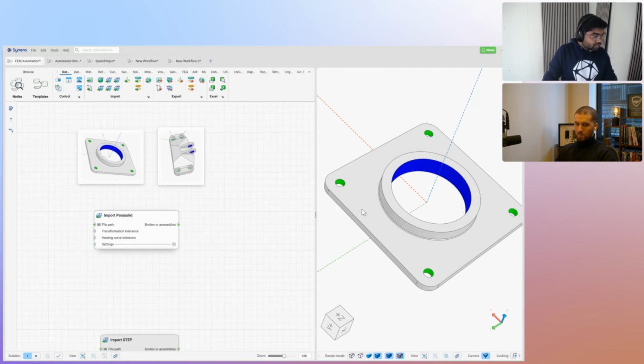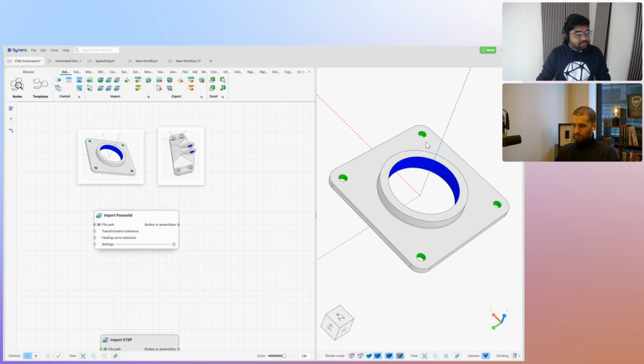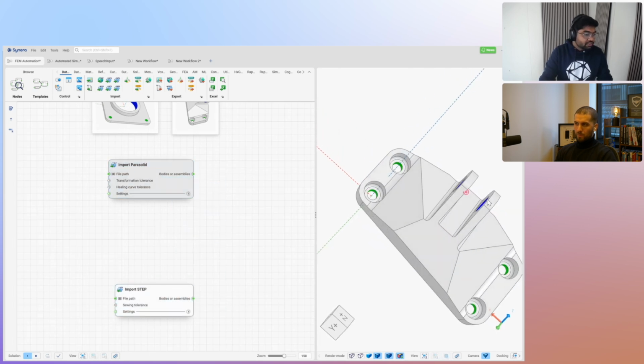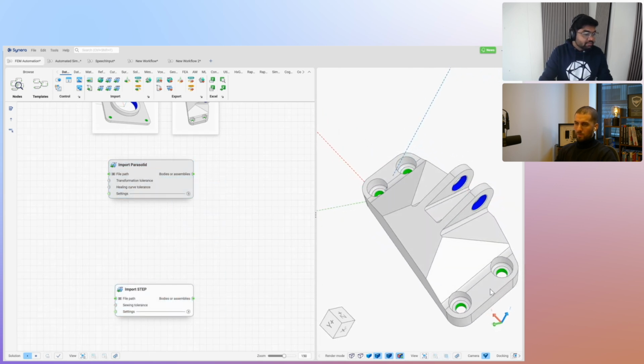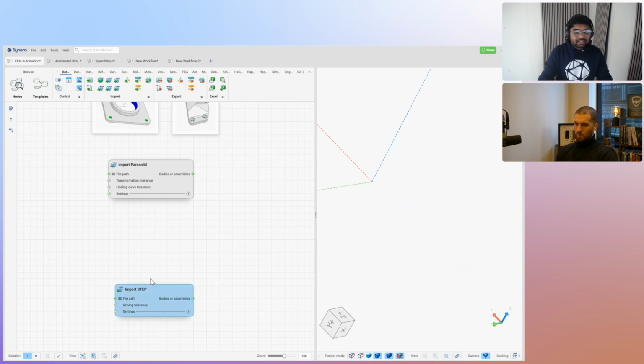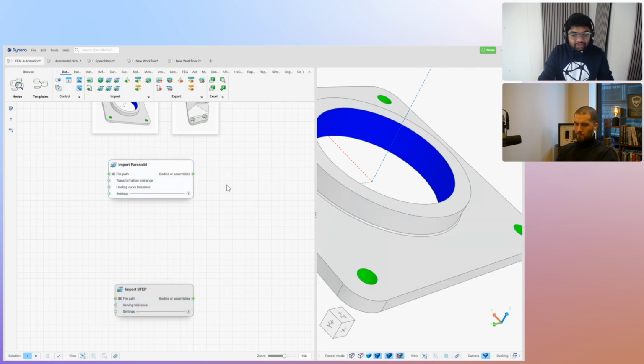Here we have a Parasolid part that we are trying to import and perform a static case, a linear static analysis, on this geometry, where these regions colored green will be fixed, and then we apply a force to see how this geometry behaves under the loading scenario. And then we also have a different geometry which has similar attributes, the same attributes with the color data, and I will tell you why we use two geometries here and how it applies.